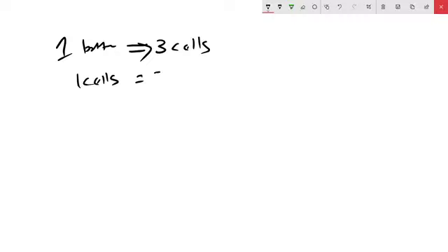So just listen carefully. There are 3 batteries connected together as shown below. Like in parallel connection, they are shown in figure. You can just refer your question. Now they are saying that each battery has 3 cells. They are having 3 cells, and one cell voltage is equal to 3 volt. So by this, one battery, the summation of all 3 cells, will give 9 volt.